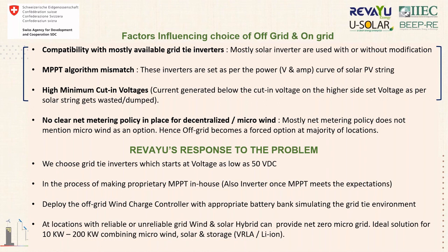Since these inverters and batteries are DC, in both cases we first convert the generated AC power to DC power. Whenever there is a conversion, there will be a loss. Then, to feed the load, the DC power through the inverter is converted again into AC power, and again there will be some loss.